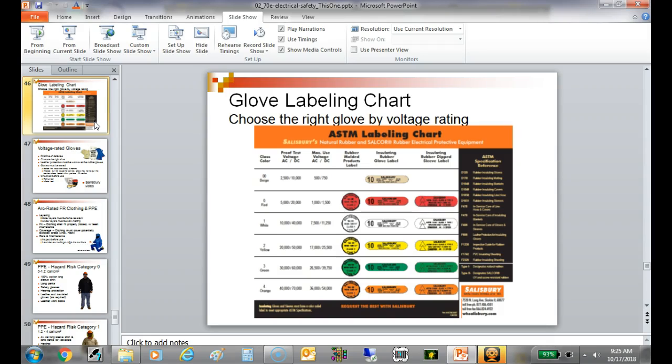So does 600 volts require level gloves? I would imagine in an industrial environment it would, but in other applications it might not. That's a question where the odds are it would. But 240 volts might be required too, if there's enough energy. If I have 240 volts fused at 200 amps, then I'll probably have to put on some PPE to work on that. Somebody wake up Anthony about that.